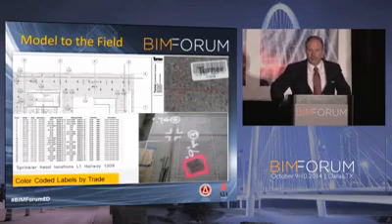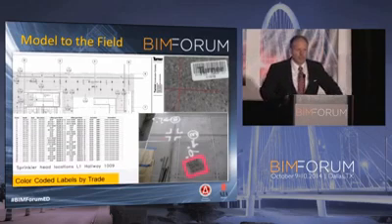Use your data again. Don't have the guys label. Pre-print the labels. Those creative guys in the field, those 7 trades out there, now their points are all color-coded. So each trade's got a colored label on it. They can walk out there. Can you imagine pouring your floor the next day, 7 total stations on the floor, all the layout done at once? They're going 460 points a day.